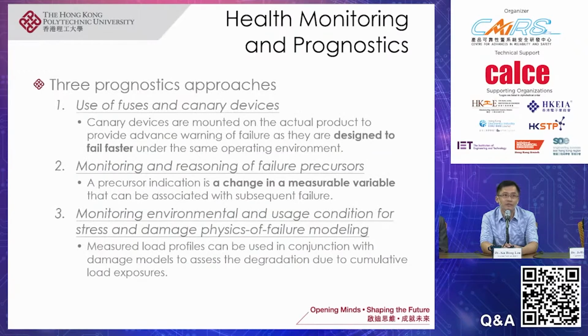Basically, there are three prognostic approaches currently used, and due to time constraints, I will not go through the details. I'm just going to summarize the main points here. The first method involves the use of fuses or canary devices. Basically, fuses or canary devices are designed to fail faster under the same conditions as everything else, so they provide an early warning signal of the failure of the system.